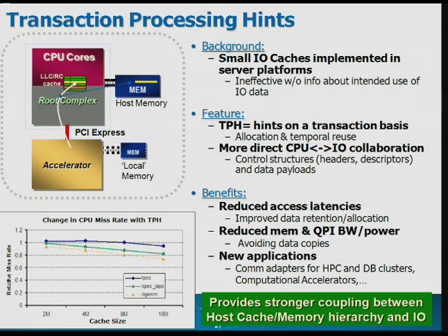I'll try to illustrate with a few examples that it would actually help reduce, first, the overall usage of links like HyperTransport cache coherent or QPI, which we call system interconnect cache coherent links, and also reduce the footprint that I/O traffic imposes on the memory subsystem, meaning there will be fewer memory transactions, and that will give you back bandwidth and reduce the power.